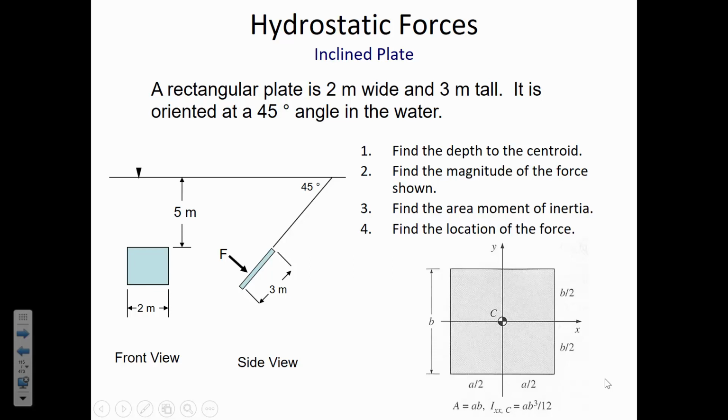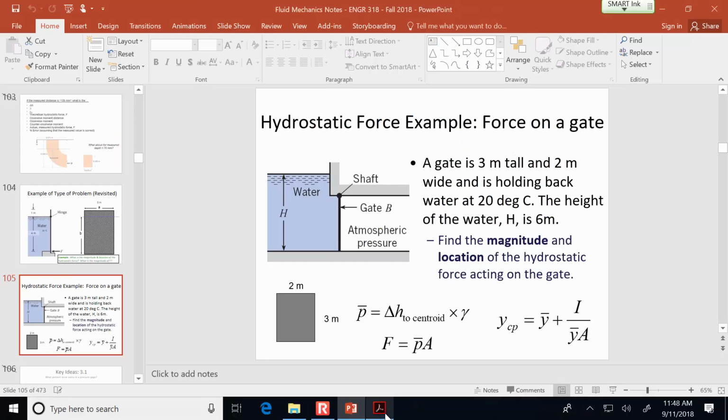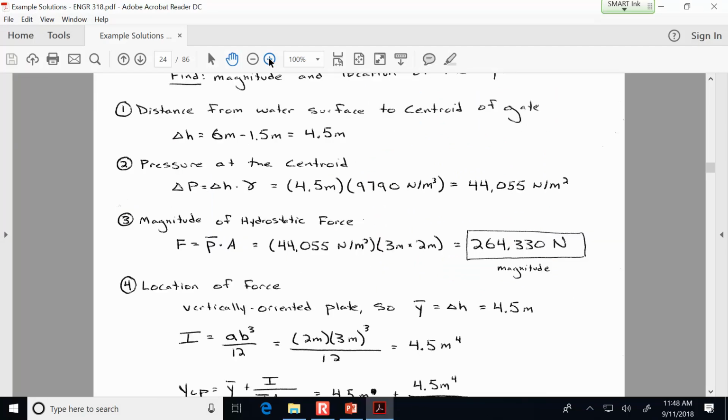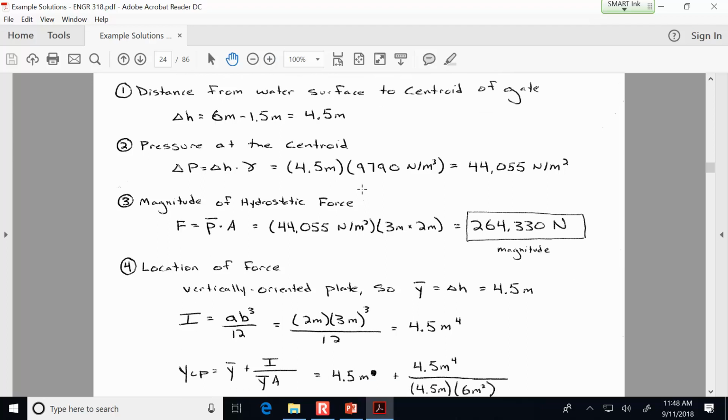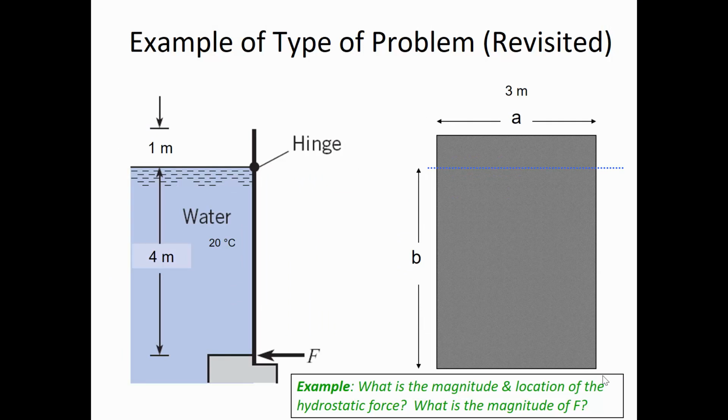All right, so here's a tricky one. When you calculate the area that you use, I think it was the third section. That's when you only use 50 by 3 and you don't include that top section. The area of the plate is the area that's in contact with water. So in this second example, the entire plate was in contact with water, but in this first one, the area that we used was just the submerged part. So we neglected this top part of the plate because it was in contact with air in the first example.